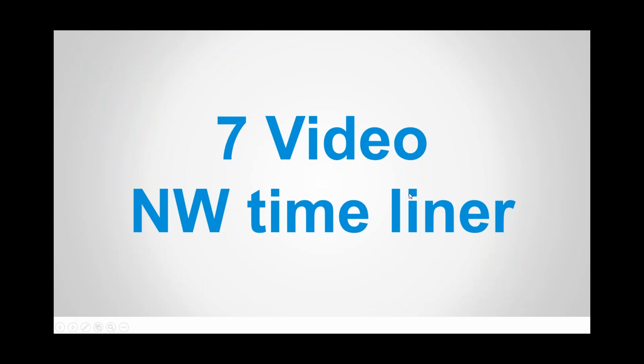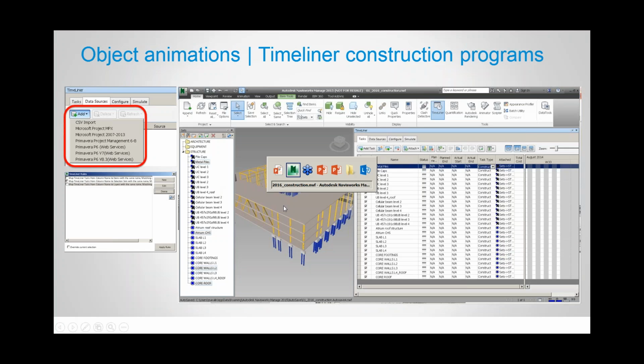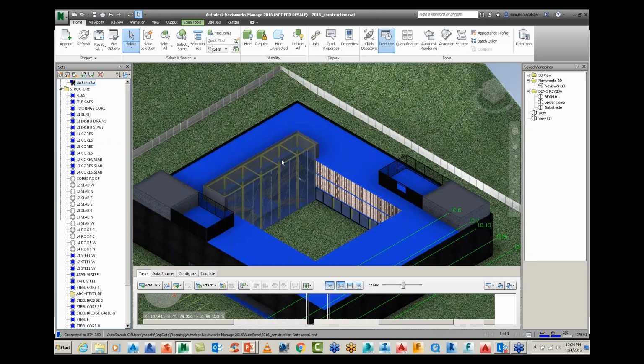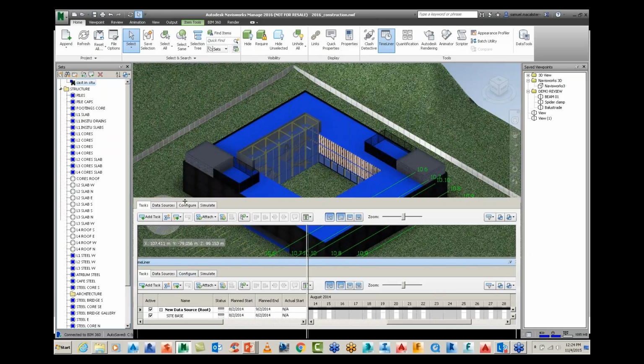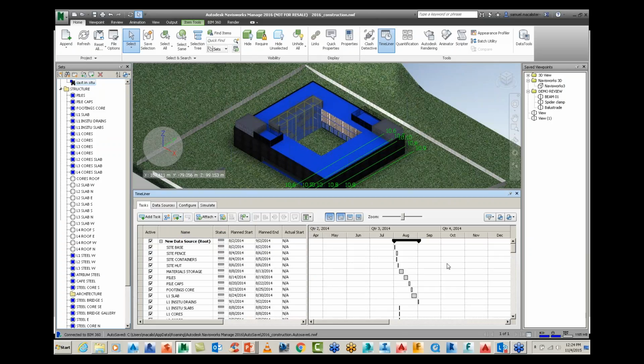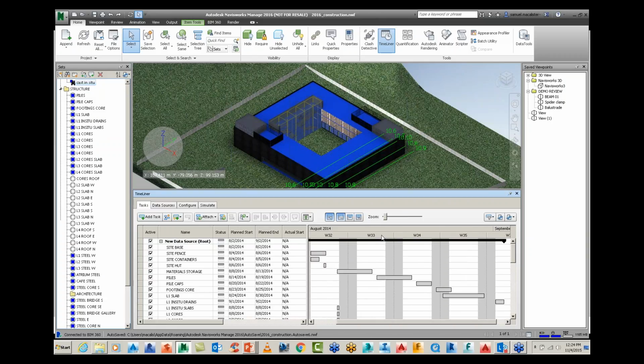Then what you do is you go to the AutoTask tool. So let me just go back a little bit. So selection sets, and I go to my Timeliner. And I won't do this right now because it just takes a little bit of time and I need to double check. What you've got here is you can do AutoTask, and for every set, for example, it will go through and do it. So let me just undo that because I don't want to destroy what I've already configured. But that's essentially what you can do. So you can see when I clicked on that for every set, it went and aligned it all together.